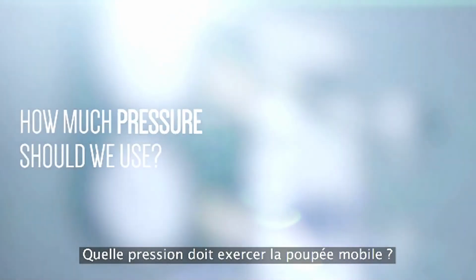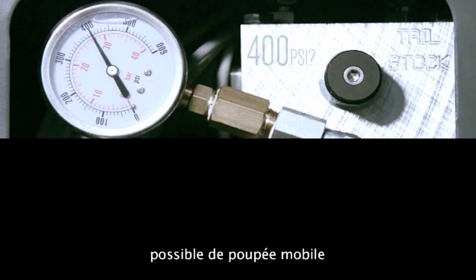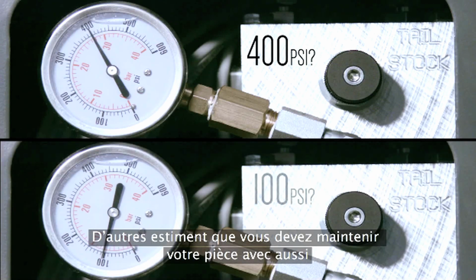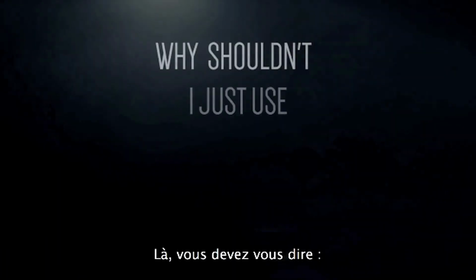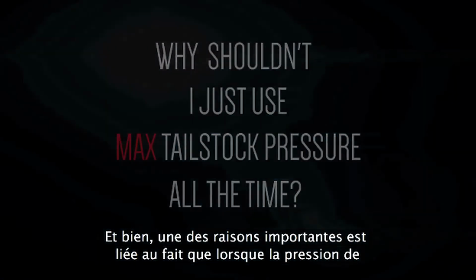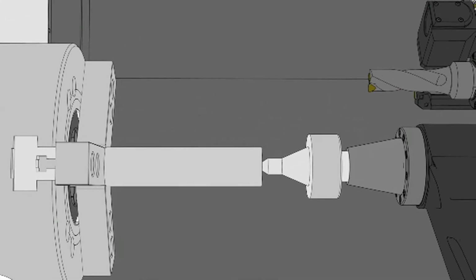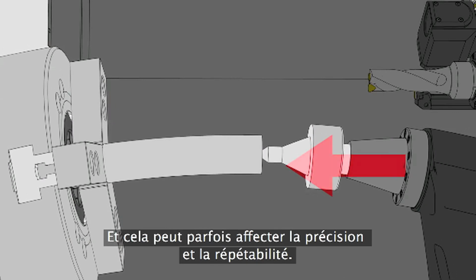But one question remains: how much tailstock pressure should we use? Many machinists believe it's best to use as much tailstock pressure as possible so the part doesn't come out. Others believe you should hold your part with as little pressure as possible so you don't deform your part. You might be thinking, well, why shouldn't I just use max tailstock pressure all the time? Well, one important reason is, as tailstock pressure increases, deflection in the workpiece and in the machine also increases. Sometimes this can affect accuracy and repeatability.